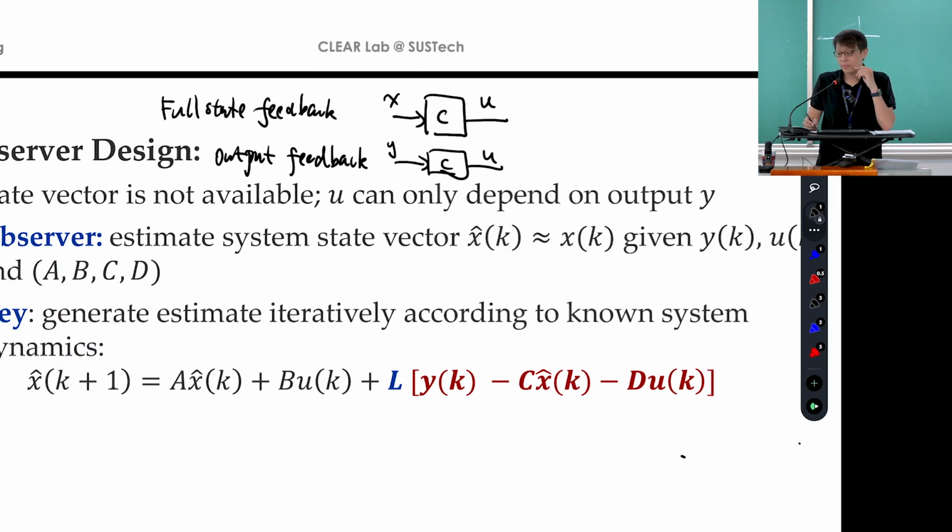It's just like the full state of any robot, at least the base, is X, Y, Z, and the roll, pitch, yaw. But if you have an IMU, an inertial measurement unit, the raw measurements are only the accelerations and the angular velocities. The other things you have to estimate.